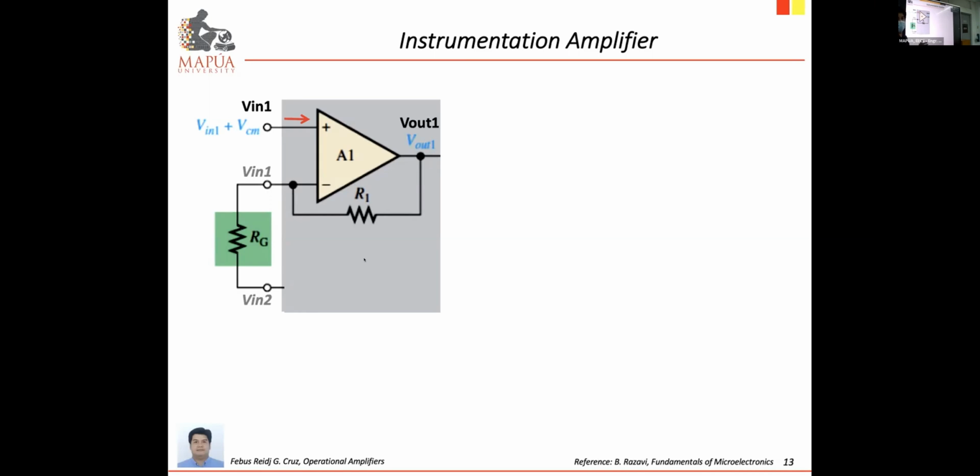Or again, in actual, there is no current, so it is actually the voltage affecting amplifier 1. Then some of that current will go back through feedback resistor R1. And on this node, it will become input current and current flowing through RG, the gain resistor. Apply the current equation on this node: current along R1 equals current along RG plus I in.